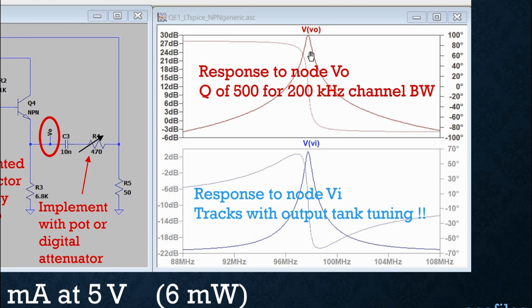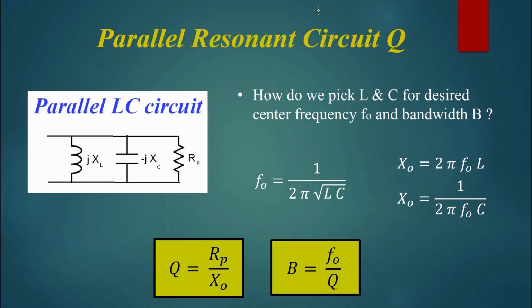Now, in Radio Design 101, we learned that bandwidth is related to something called Q, or quality factor. And here's a slide from that Radio Design 101. This is actually from episode 1, and we talked about the circuit Q. For a parallel tank circuit, which is what we have, the Q, the number, is equal to the resistor divided by the reactance of either this or this element.